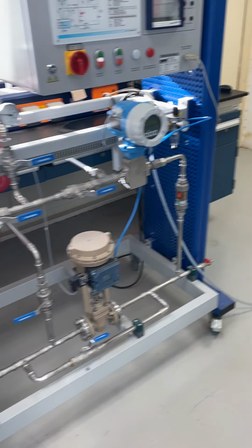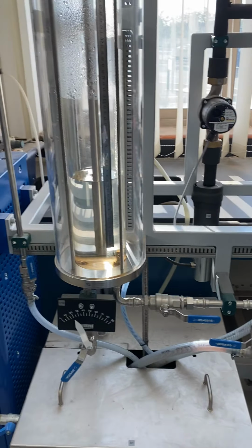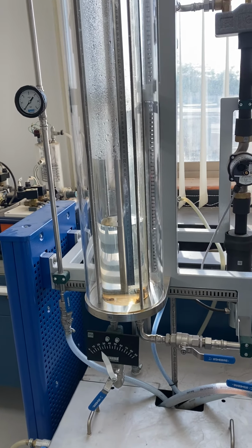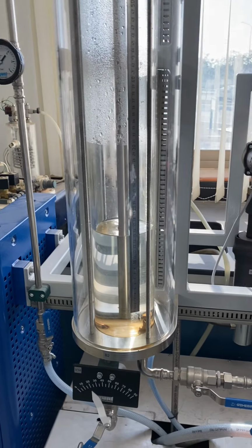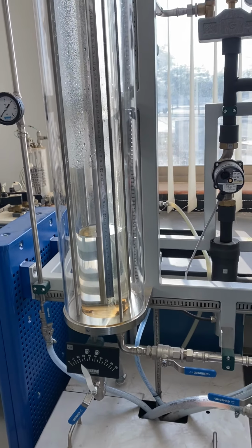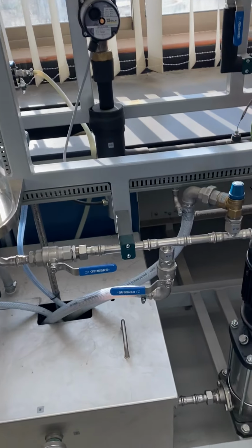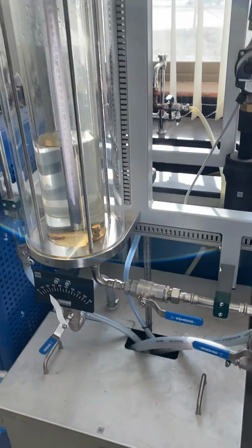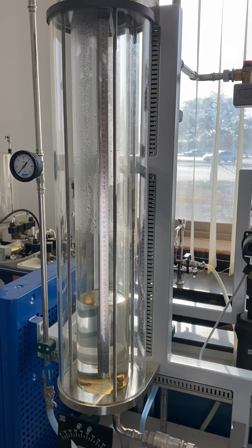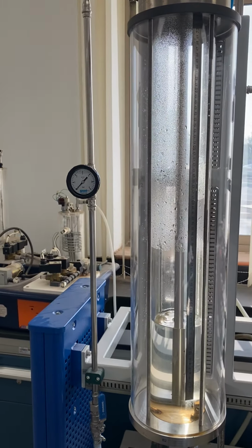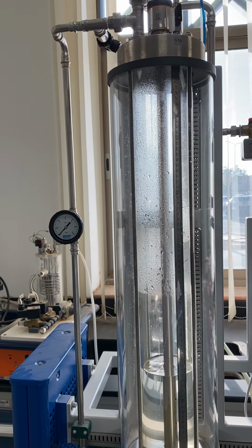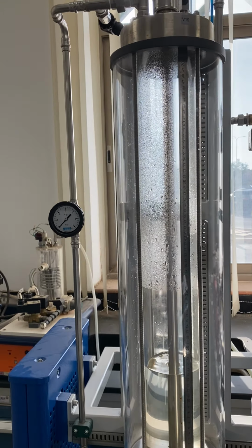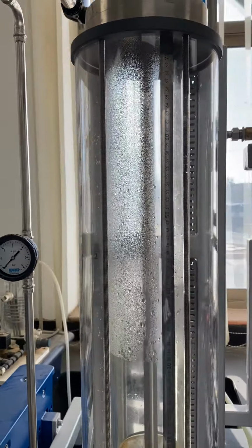So basically, as I said, guys, the control variable in our experiment is liquid level inside this tank B2, and in order to control the level inside this tank, we will manipulate water inlet flow rate to the tank. In this experiment, the tank is considered to be a fixed roof atmospheric tank, meaning that the tank is open to the atmosphere.